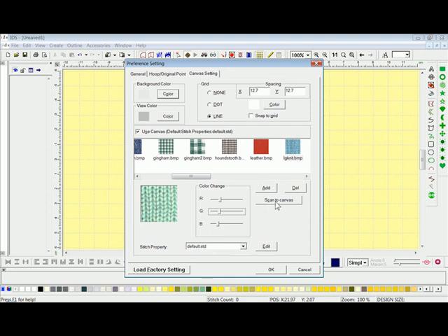You can also scan directly into the canvas settings just by clicking Scan to Canvas. This will actually open up your scanning program. You would scan the canvas in there, and then after you scan the canvas and hit the Accept button or the Scan button, whichever is the affirmative, then it will actually scan it right into your program. The suggested fabric size scan should be no larger than 236 by 236 pixels or 0.6 by 0.6 inches in size and between 300 and 400 dpi. The reason is that when you do scan it in, it scans in a little swatch of the canvas and then it repeats that canvas over and over in the background.